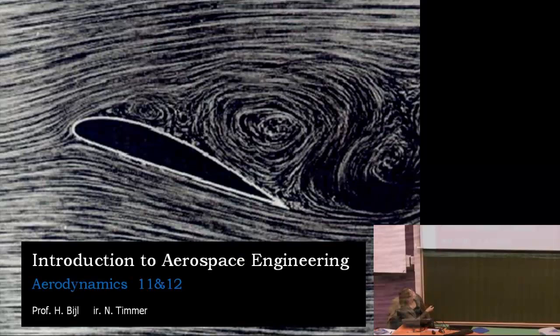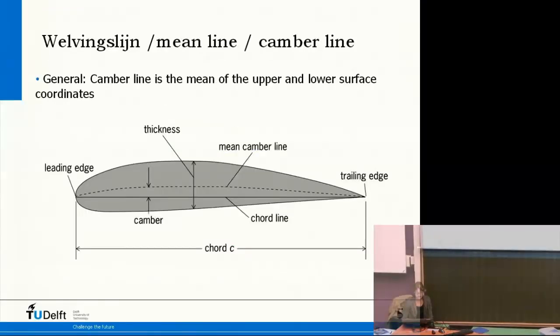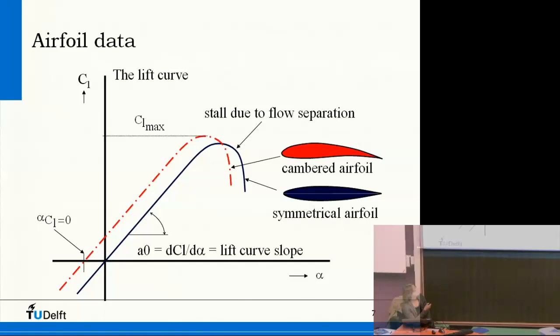So this airfoil is stalling, is fully stalled at this angle of attack, and you see the flow is not following it, except maybe for a tiny, tiny bit, and then separating. And you get this large vortex in the dead water region. So that's happening there, and that's quite important. As you see, the lift drops non-linearly, so quite dangerous. So you should be aware what the stall angle of attack is at certain speeds. And it depends on the speed because the speed is in the CL max.